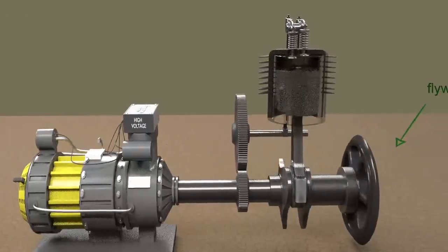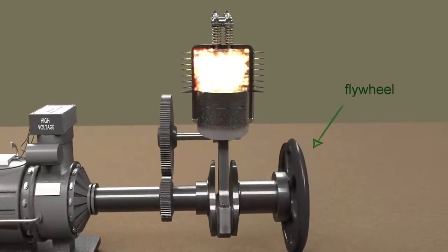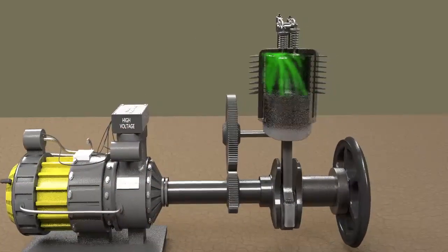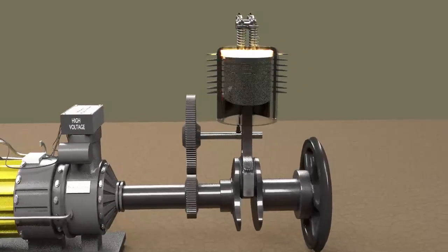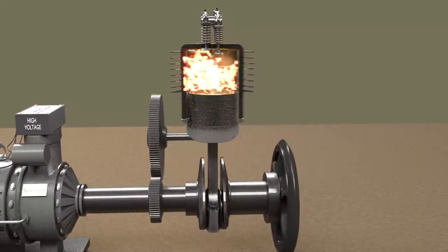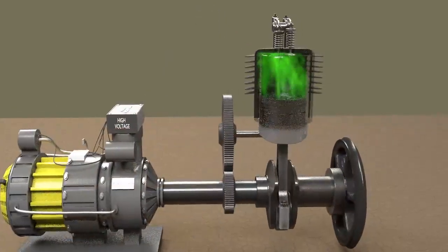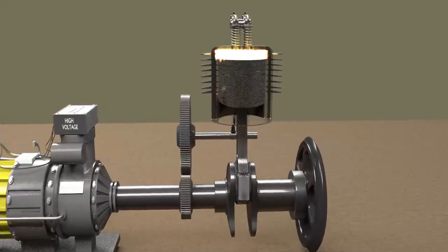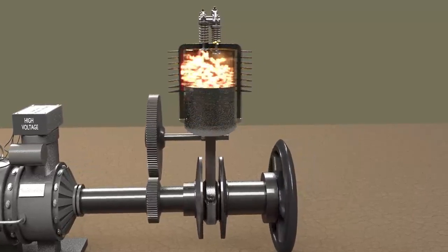A flywheel is connected to limit this fluctuation of speed. A flywheel is a wheel with high moment of inertia, which means more energy is required to increase or decrease its rotational speed, or in other words, to accelerate or decelerate it. When excess energy is developed by engine during power stroke, the excess energy is stored in flywheel with overall smaller acceleration. And when energy is required by engine during compression and other strokes, the energy is provided by flywheel by decelerating itself by a small amount. Thus, flywheel reduces the fluctuation of speed of engine.